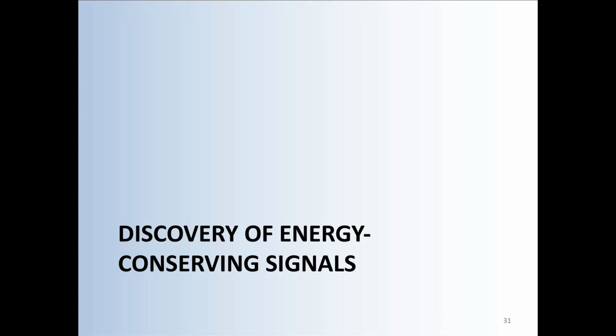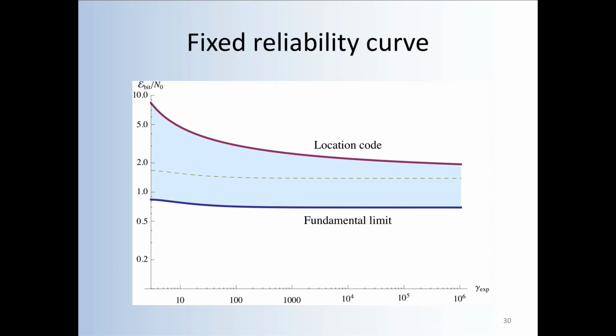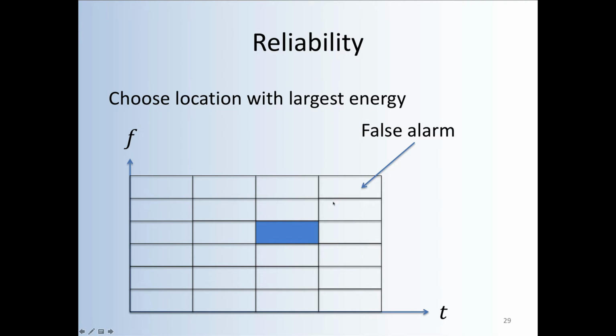Now the question is, if we used a signal like that, let me point out first of all that this kind of signal is, you would argue, dictated by two things. First of all, the characteristic of the signal is dictated by the ISM and the fact that it has this coherence time and this coherence bandwidth. And if we were to violate the coherence time and the coherence bandwidth, we could probably still communicate. However, we would suffer a penalty in energy. We would have to communicate with a larger amount of energy per bit.